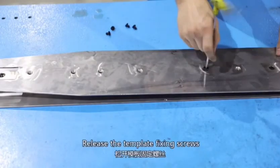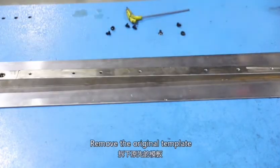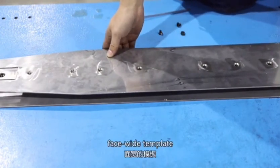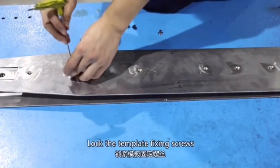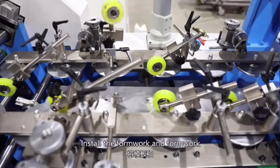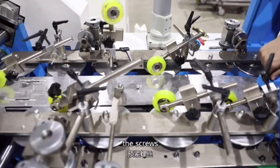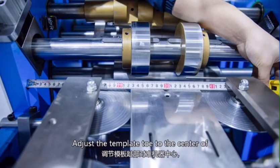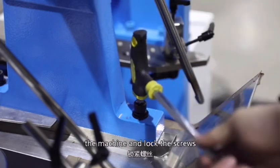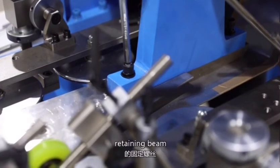Release the template fixing screws. Remove the original template, changing with the required face-wide template. Lock the template fixing screws. Install the formwork and formwork retaining beam back and pre-tighten the screws. Adjust the template toe to the center of the machine and lock the screws. Lock the fixing screws of the formwork retaining beam.